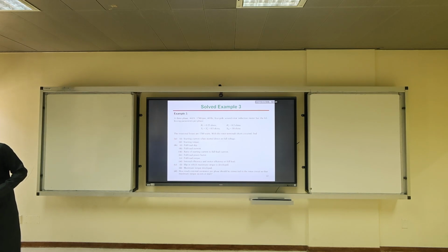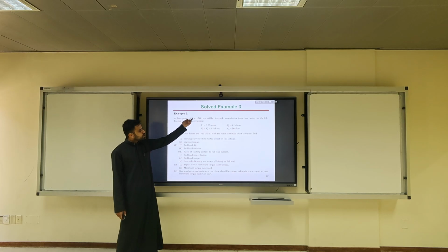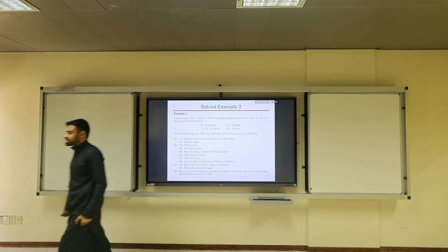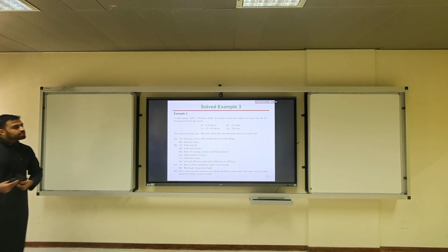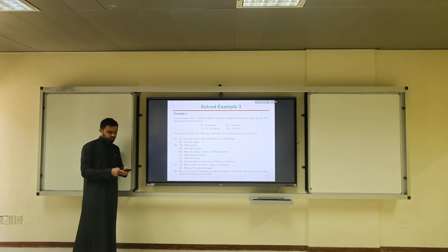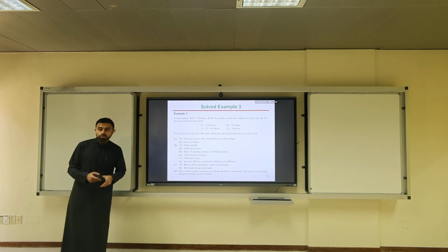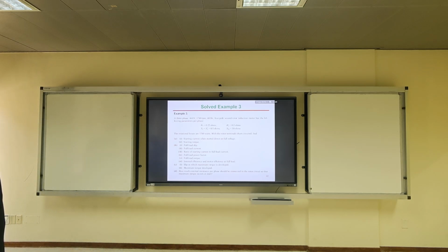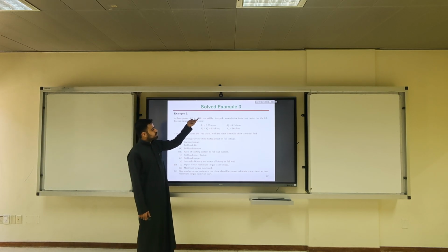Let's try to solve it real quick. A 3-phase induction machine, 460 volts, that's line to line, 1740. So what's the slip? Calculators. 1800 minus 1740 over 1800. So the slip is 0.033, right? Sometimes it tells you the speed without saying whether this is the operating speed or the rated speed.